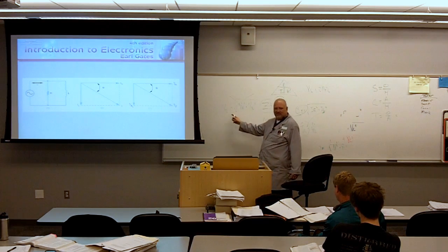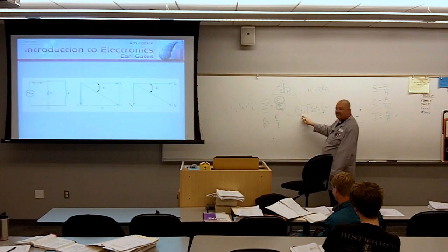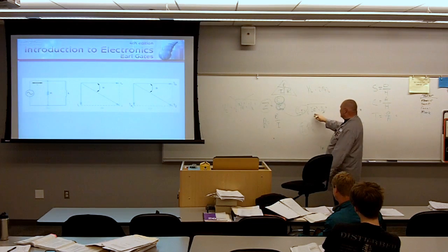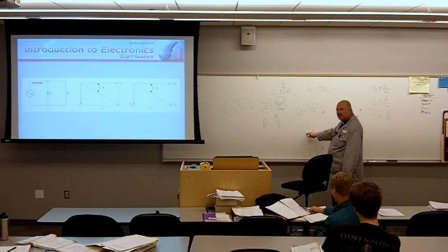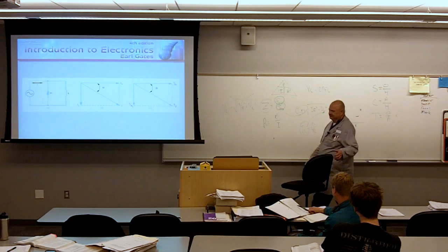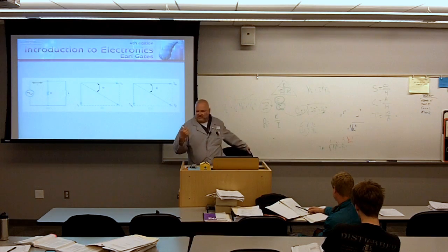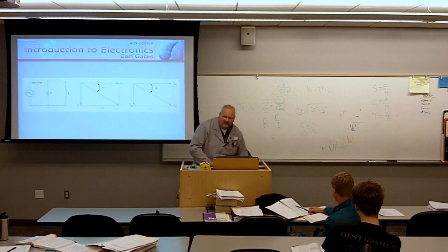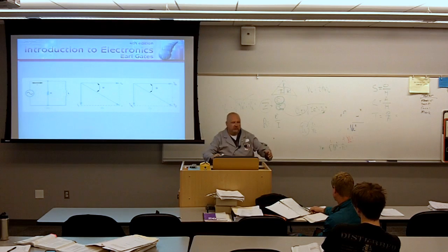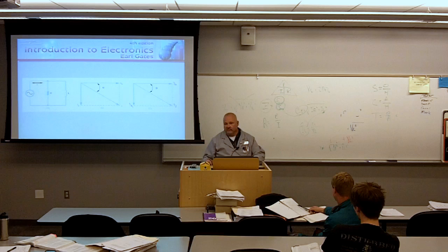Okay? You want to calculate out your total impedance. Z is equal to E over I. I, you get from IT. I is the vectorial sum of current through the resistor, current through the inductor. You calculate out current through the inductor by calculating out voltage of the inductor over inductive reactance. A lot easier. So don't do what the book tells you to do. If you want to play with this and just see if you can do it, and hey, look, Mom, no hands, cool, do it. But beyond that, I'd stay clear of that formula.